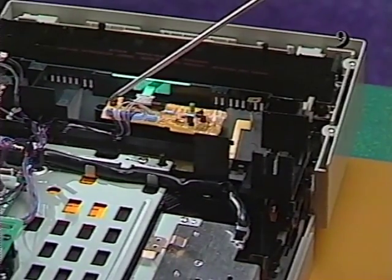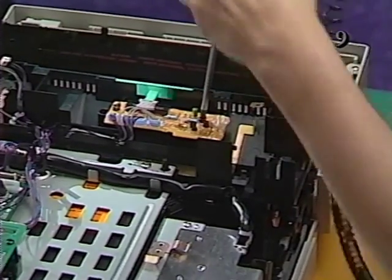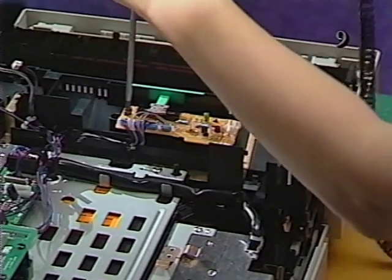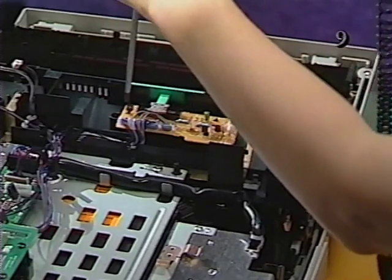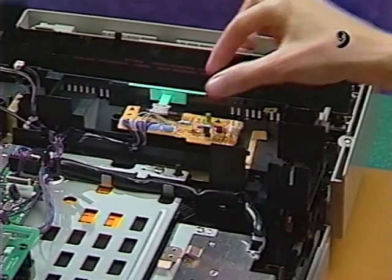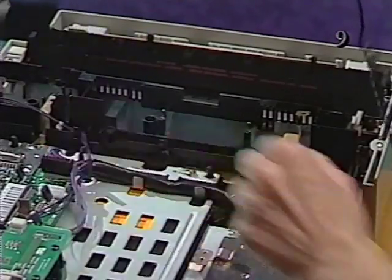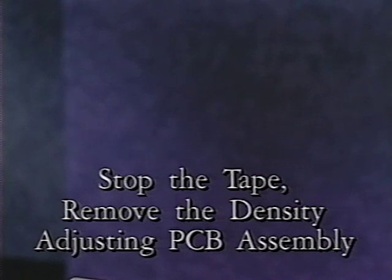Remove the two black screws and washers that secure the density adjusting PCB to the inner cover. Finally, lift the density adjusting PCB and connecting cables out of the printer. Stop the tape and remove the density adjusting PCB.